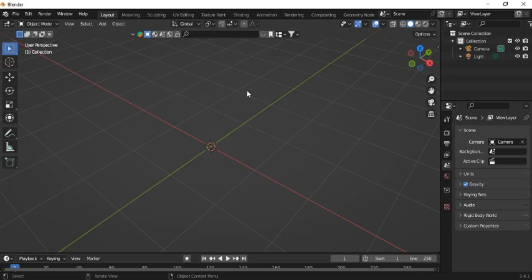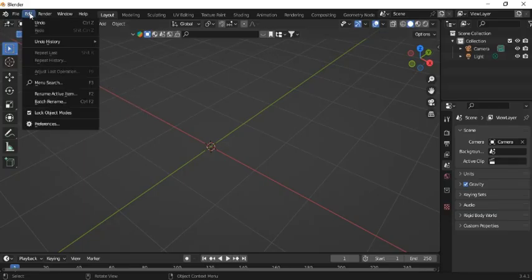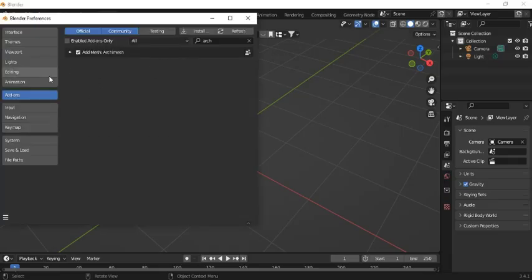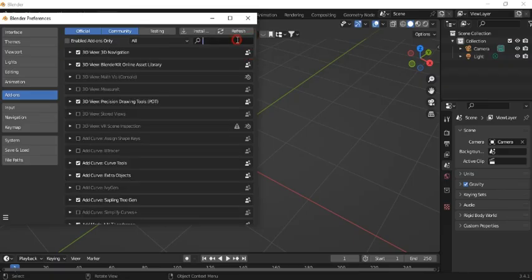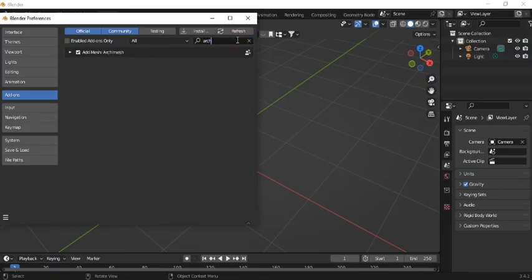Sorry, your voice cut at some point, so I couldn't really get it. Let me take it again. I said you click on the edit, click on preference, go into your add-ons, and inside here type Archi. And then you check this box. When you check the box, you just click here and you click on save. Do we understand that?